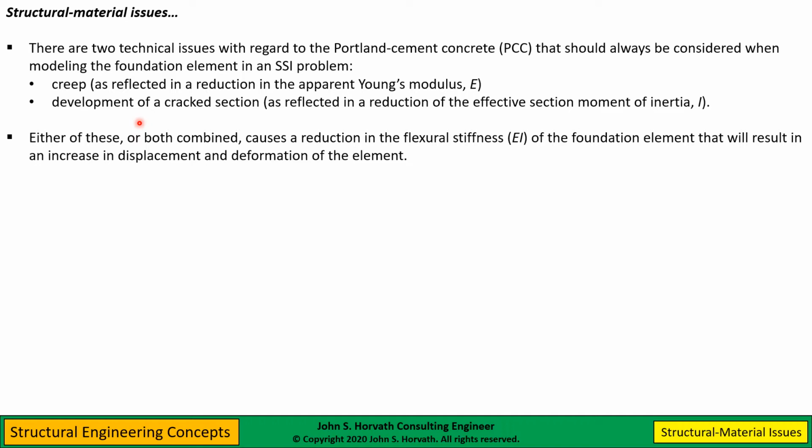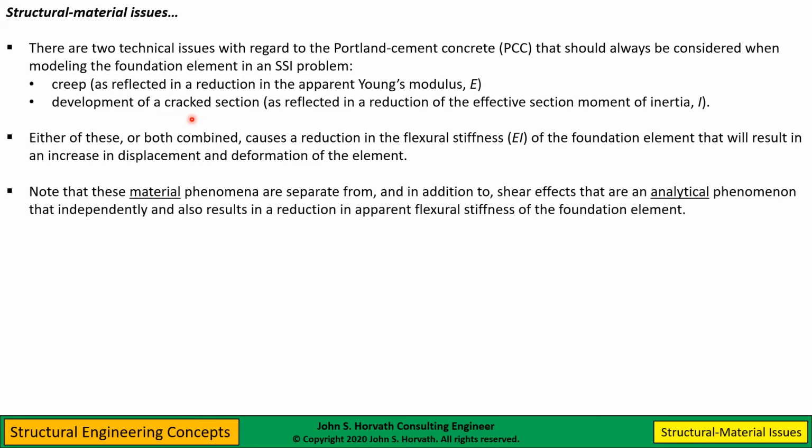We want to consider all the things that go into reducing the flexural stiffness of this foundation element, because we want to always analyze and design for the worst case scenario, realistic worst case scenario of this behavior. And I do want to emphasize that these two phenomena of creep and cracked section behavior for Portland cement concrete, these are material phenomena. They're separate from, but they are additive to the shear effects, which are an analytical phenomenon.